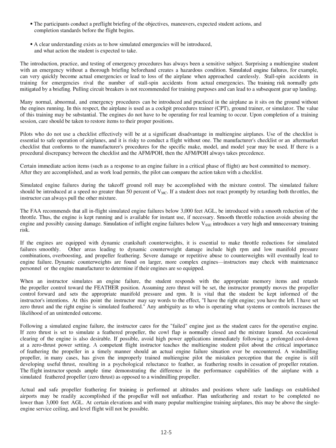Pilots who do not use a checklist effectively will be at a significant disadvantage in multi-engine airplanes. Use of the checklist is essential to safe operation of airplanes, and it is risky to conduct a flight without one. The manufacturer's checklist or an aftermarket checklist that conforms to the manufacturer's procedures for the specific make, model, and model year may be used. If there is a procedural discrepancy between the checklist and the AFM/POH, then the AFM/POH always takes precedence.